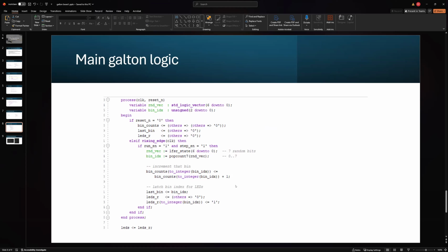Now this is the process block that we use for the final logic in our code. The reset part is doing this: if the reset is 0, or on in this case. I know it's kind of counterintuitive because usually it means the other way around, 1 is on and 0 is off, but 0 is on in this one.